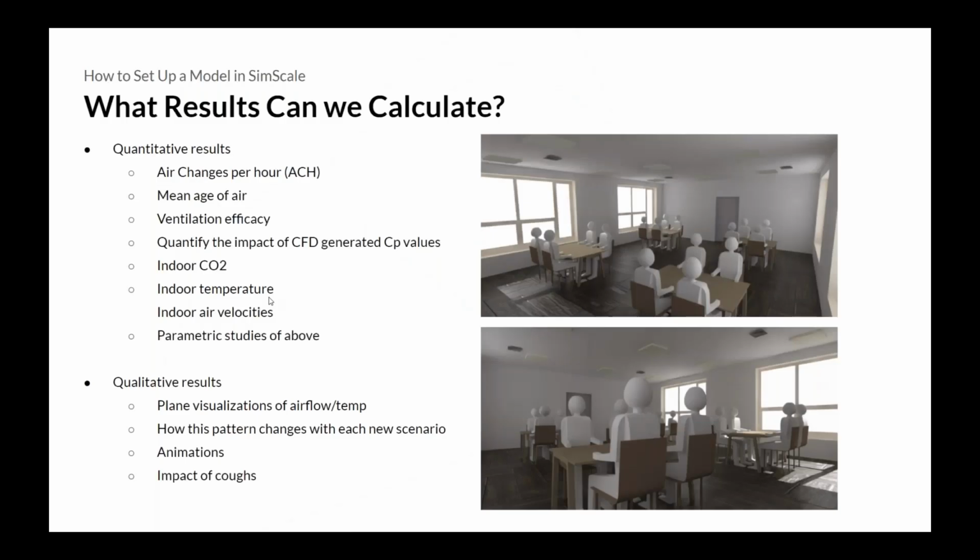Now, just a little bit to conclude on what we've seen. So with CFD, you can definitely get a lot of insights that inform your design decisions for ventilation strategies. You can get quantitative results that give you the number values on the amount of air changes per hour, the mean age of air in the room, ventilation efficiency, obviously temperature and air velocities within the room. But it can also give you CO2 concentrations, for example,